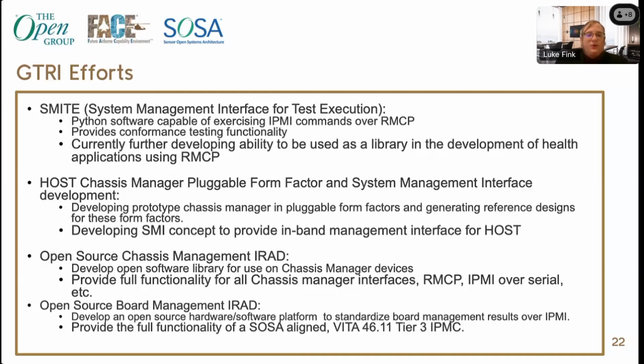And then, as mentioned before, the primary topic of this presentation is the open source chassis management internal research and development project, which was to develop an open source library to use on the chassis manager itself. The goal of that is to provide full functionality for chassis manager interfaces, so implementing IPMI over LAN, serial, and some baseline functionality for event handling and logging, as well as providing a library to implement each of those messages in the IPMI standard.